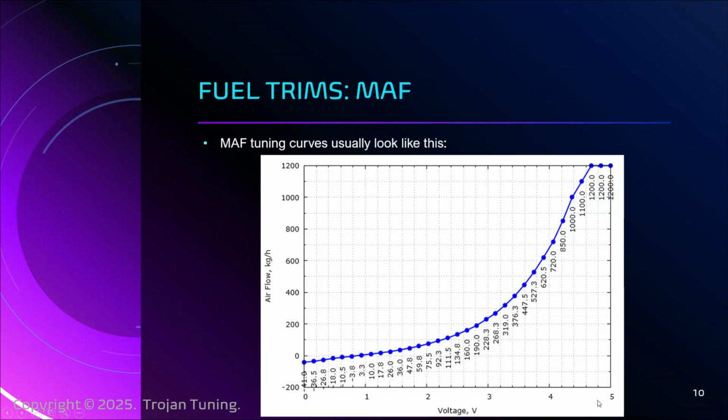This is DC voltage, and it corresponds to, within the mass airflow sensor, it's a little like a pinhead, right? So into your airstream drops this little thin wire, which at the end of it has a little round tip, like a pinhead, right? And as the air flows over that pin, it has a cooling effect.